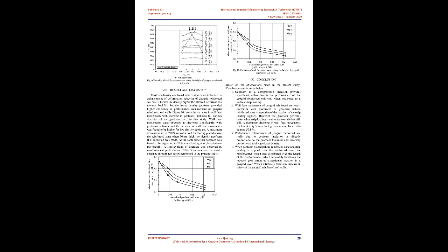Figure 7 shows the displacement vector diagrams for geogrid reinforced soil walls without and with geofoam when the footing is placed over the reinforced zone. Comparison is made between 2 identical models with and without geofoam at a maximum footing settlement of 15 mm, i.e. S/B equals 0.6. Vectors in the figure are scaled up 2 times from the original for better visualization of the results.